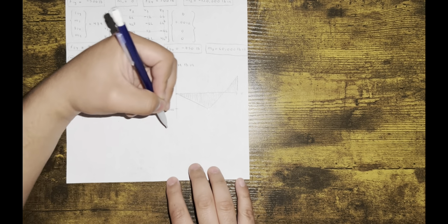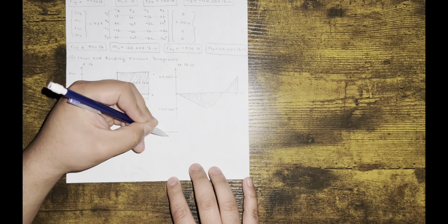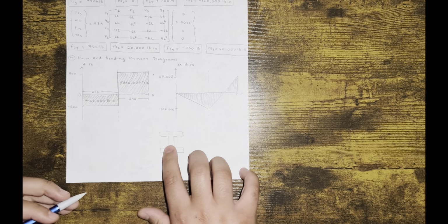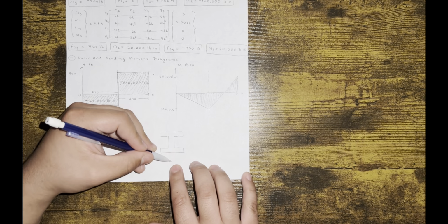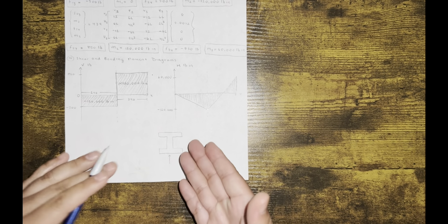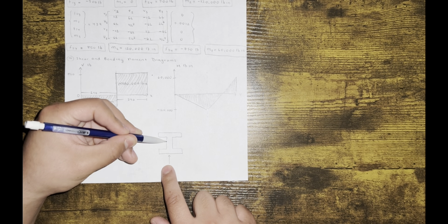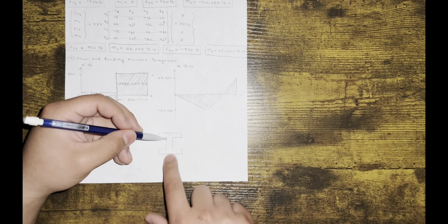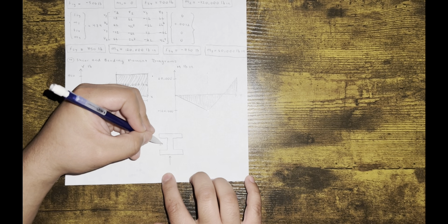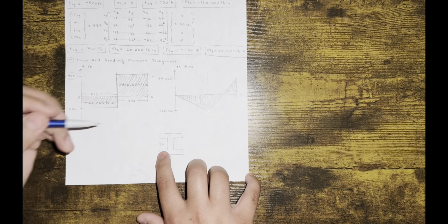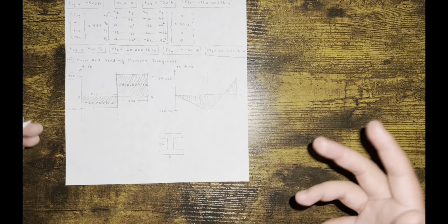So if you were designing a beam, right? I don't know, an I-beam. Let's take an I-beam, for example. Well, we know shear loads your webs, okay? So as soon as vertical shear is introduced, this could be the cross-section of an aircraft. This could be a beam in a building. It could be anything. But you need to make sure your webs can handle 180,000 pounds, depending on how much your height is. And just to keep it very simple, if this is 20 inches in height, divide 750, which is your max shear, divided by 20. That's going to give you some number, right? I don't know off the top of my head. 37.5 maybe.